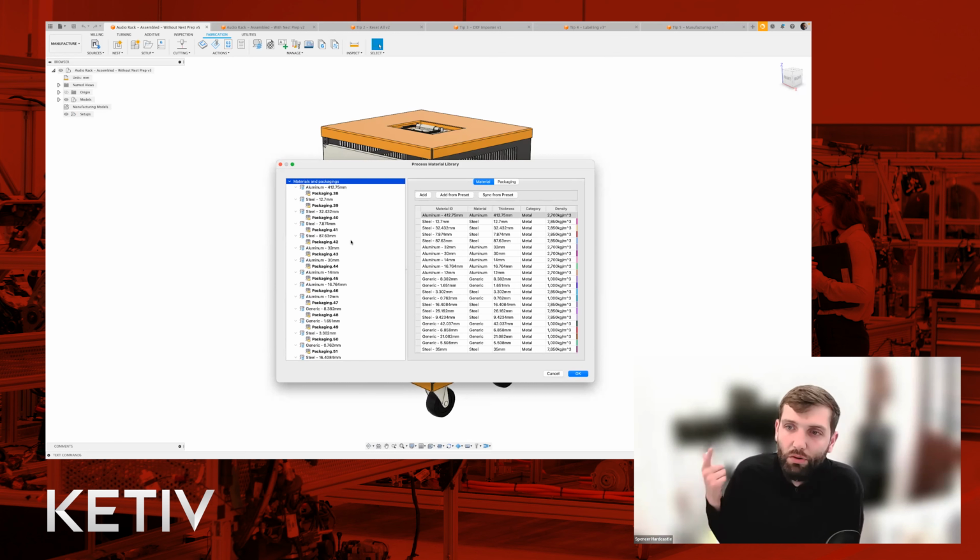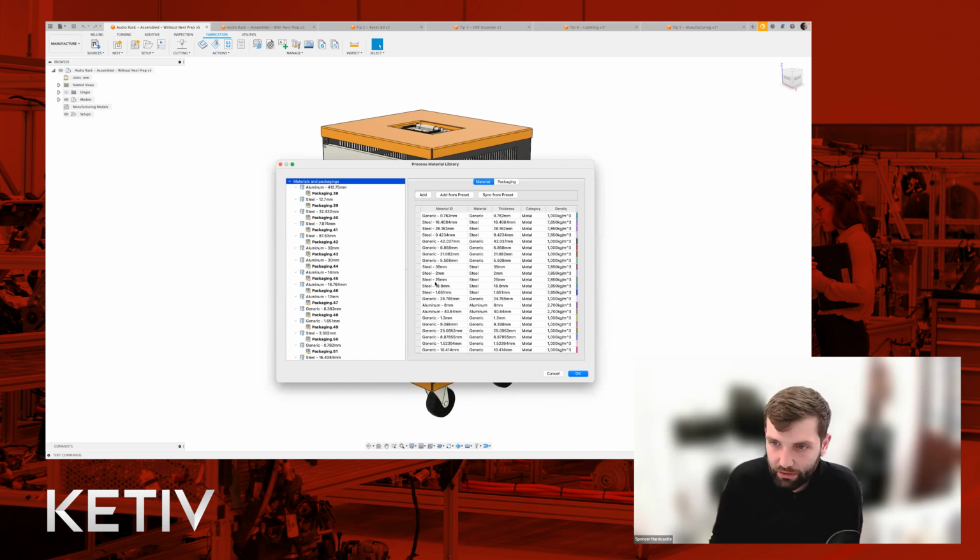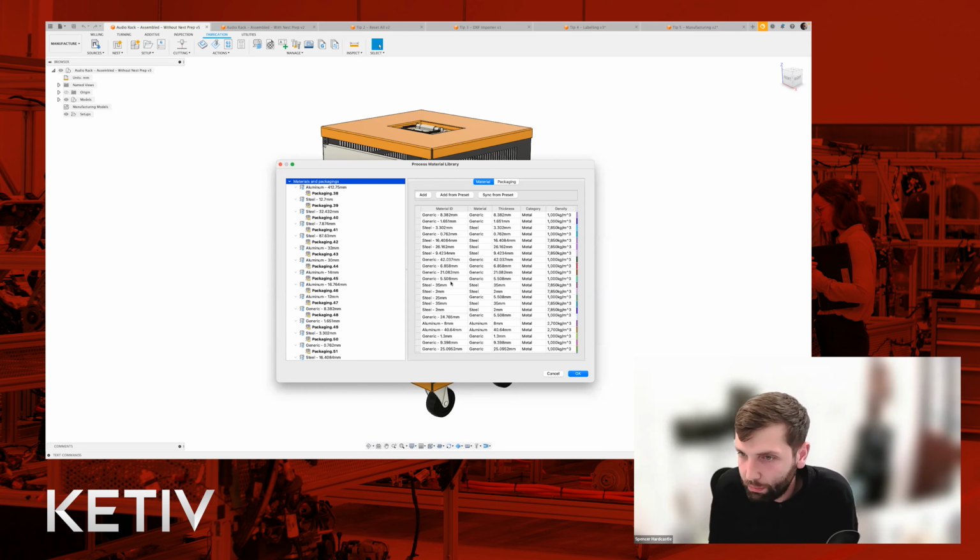This is the number one reason why people get the Nesting and Fabrication extension and then don't use it. It's the idea that they get this far, they're presented with this sea of materials that they don't understand, and then they can't go that next step. And you can see it here, right? Like you've got materials here, for example, 42 millimeters thick. I mean, you can nest on something 42 millimeters thick, but definitely not in this design.